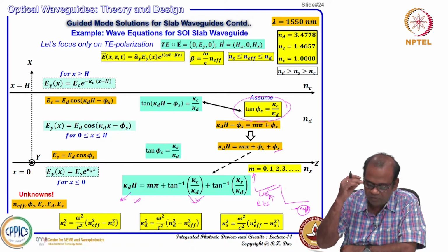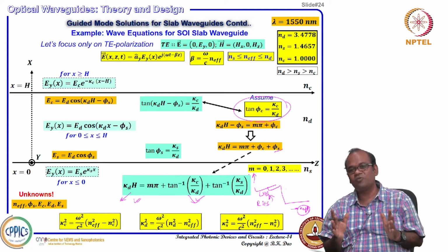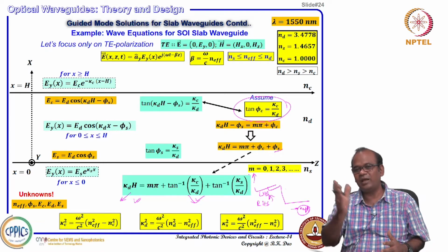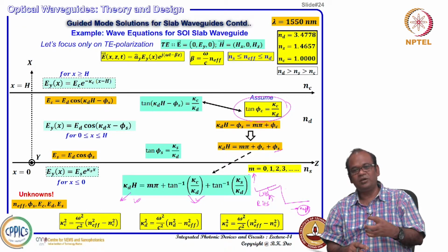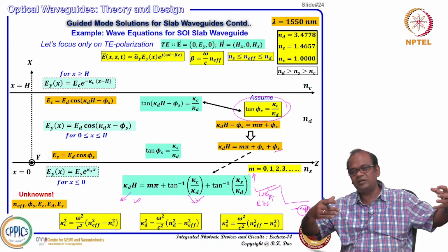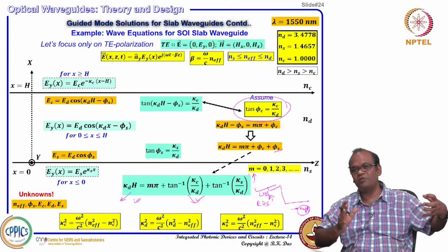The ultimate goal is this: we have shown that in the ray optics model, with theta, it is very difficult to control which particular angle you need to couple. Normally in practice we can couple light into all modes, but the ray optics picture is not giving a good understanding of how you could excite different modes, because the theta angle is controlled by Snell's law, and in principle you cannot control it.